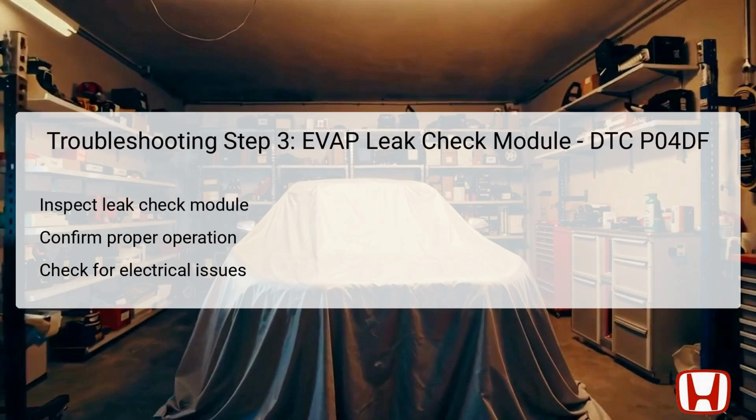The third step focuses on the evaporative leak check module's performance. This module's proper functionality is crucial for ensuring that the entire EVAP system operates as it should. Inspect the module for any signs of physical or electrical damage, which may interfere with its operation. Testing the module through the HDS or applying specific diagnostics will reveal whether it is reacting as designed.